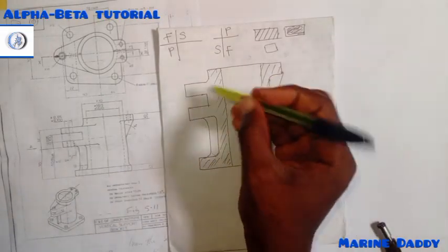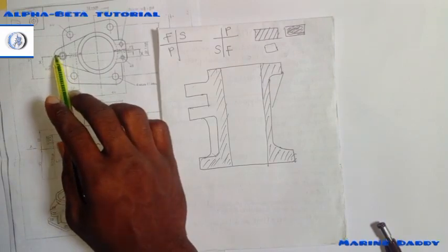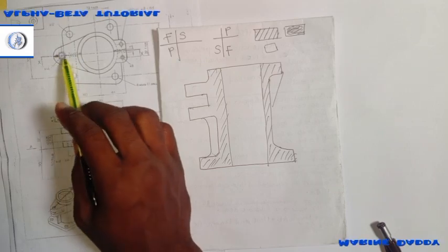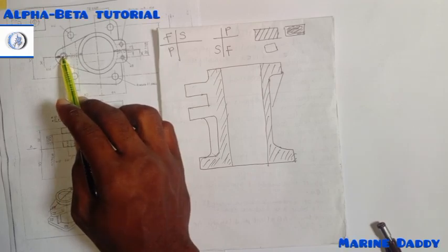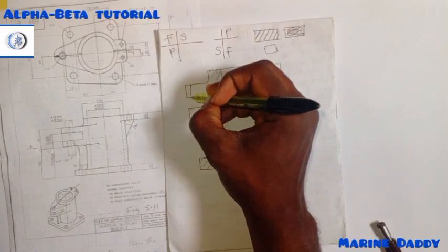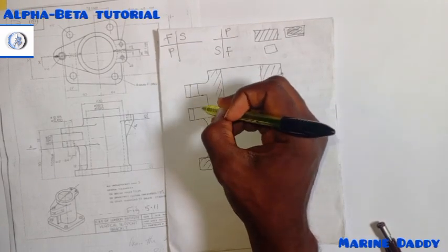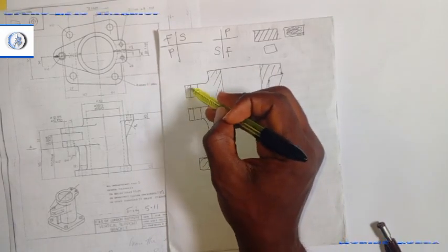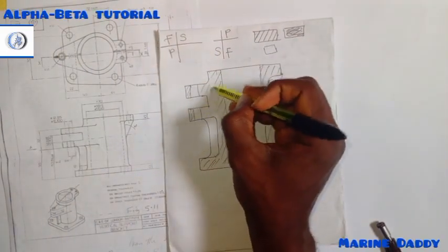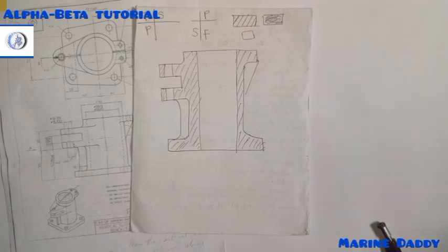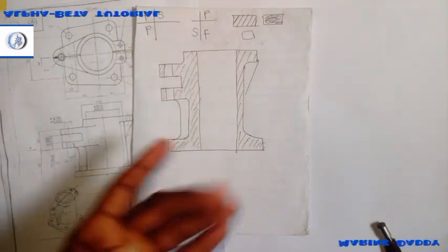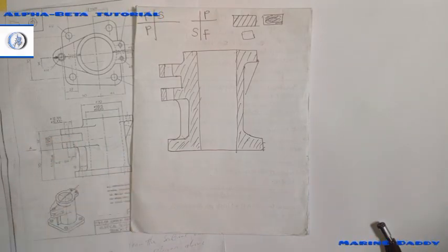Okay, let's go over to this other side. From our diagram, the plan, sorry, we can see that the cutting plane passed through the center of this hollow part. So that means that we'll have an allocation for the hollow part, which is going to be smooth. But the other side, that's this other side I told you guys earlier, is going to be rough. Then every other part of the diagram too will be rough. So this is the answer to the question. All you just have to do is to draw it with the dimensions, you understand, and that's all.